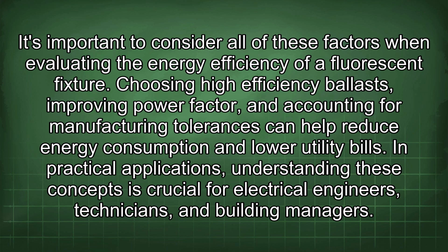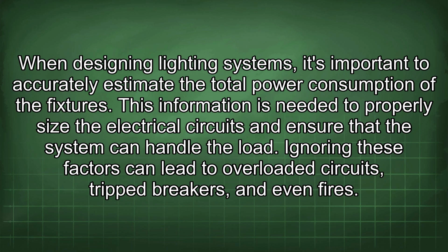In practical applications, understanding these concepts is crucial for electrical engineers, technicians, and building managers. When designing lighting systems, it's important to accurately estimate the total power consumption of the fixtures. This information is needed to properly size the electrical circuits and ensure that the system can handle the load. Ignoring these factors can lead to overloaded circuits, tripped breakers, and even fires.